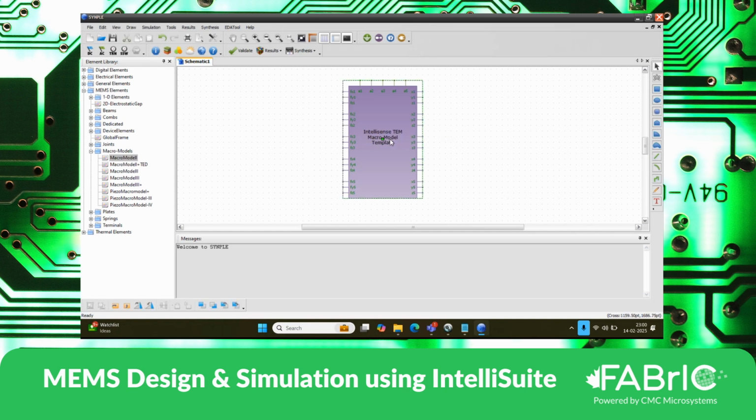In the case that I have chosen, the node of interest, node, not the mode, NODE, is only one. So if it is 1 to 3 nodes of interest where it shows maximum displacement, then we choose macro model 2. If the nodes of interest are beyond 3, then we choose a macro model 3 element.